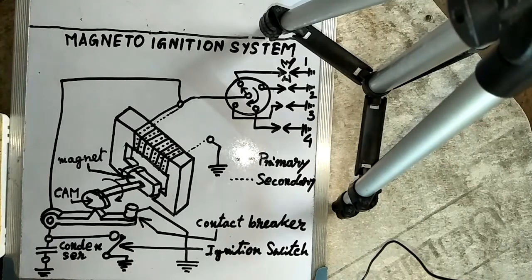A third type of magneto, called the polar inductor type, is also in use. In the polar inductor type magneto, both the magnet and windings remain stationary, but the voltage is generated by reversing the flux field with the help of soft iron polar projections called inductors. The working principle of the magneto ignition system is exactly the same as that of the coil ignition system. With the help of a cam, the primary circuit flux is changed